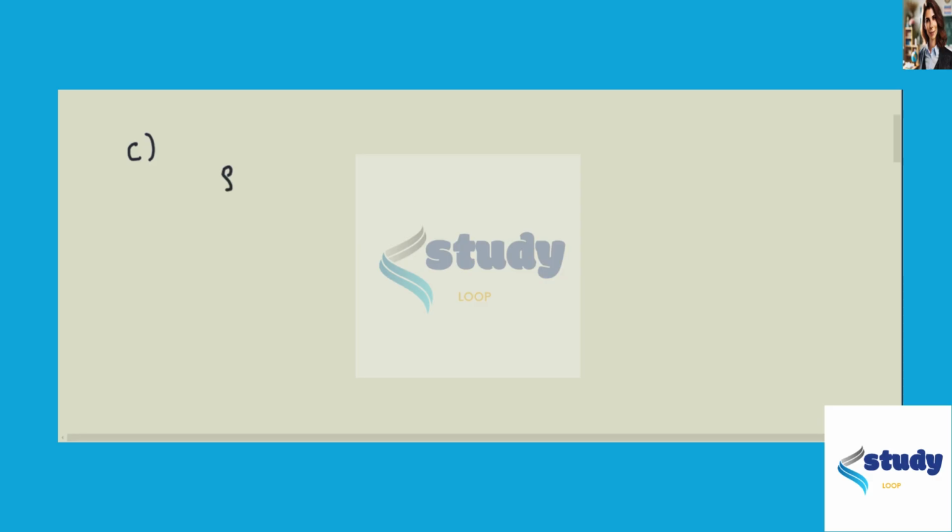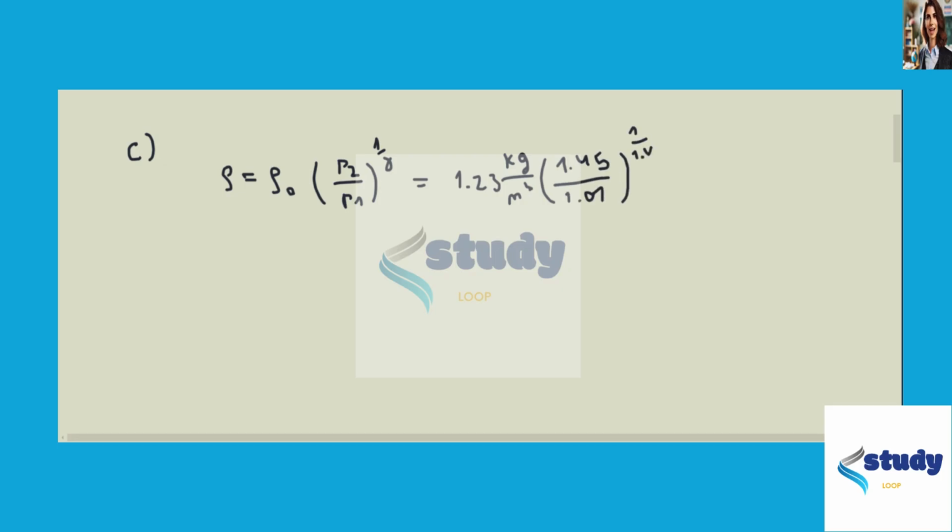So this different density is equal to initial density times P2 over P1 to the power of 1 over gamma. Substituting the known values, we obtain 1.23 kilograms per meter cubed, and here is 1.45 over 1.01, to the power of 1 over 1.4 since the gas is air. And this equals 1.59 kilograms per meter cubed.